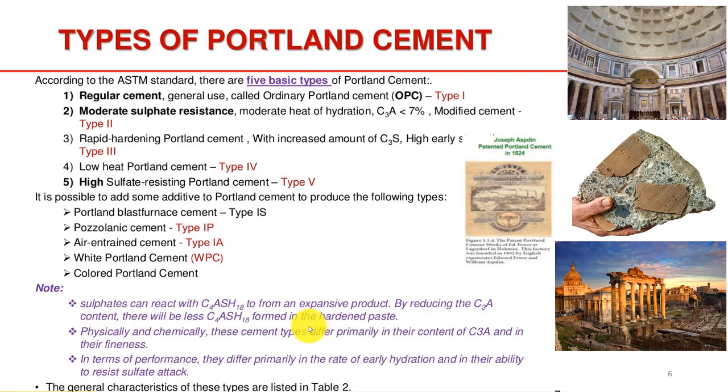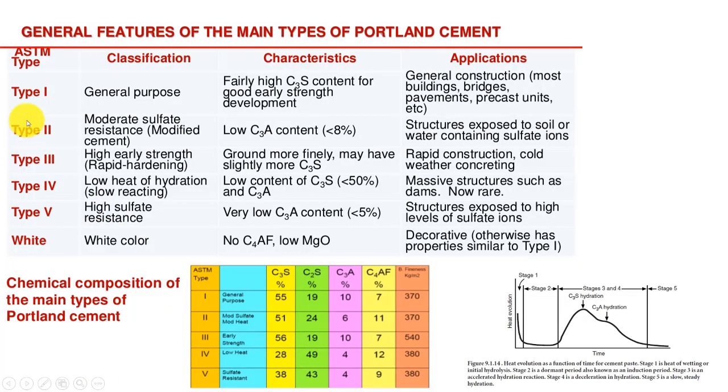So the age of a concrete, the life of concrete, reduces due to the durability aspects. Then it's chemical composition based, the type of cement based on their chemical composition that I have explained. If you're using the type 1 cement, it's a general purpose cement. It has a fairly high amount of tricalcium silicate. It would achieve the strength within the 28 days.